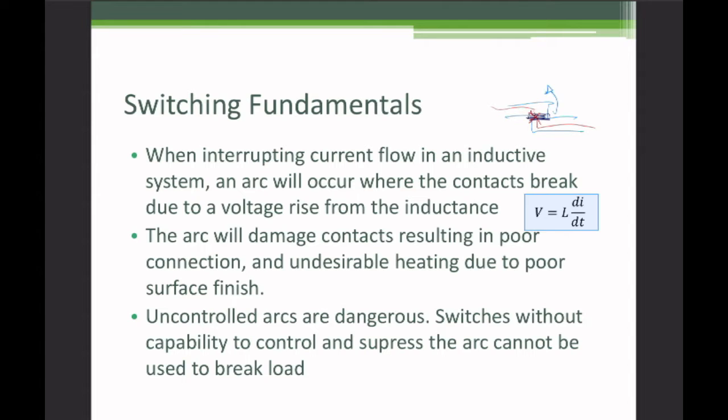In the best case, your contacts lose their temper and sort of burn away from each other. In the worst case, your switch contacts weld shut, and now your switch isn't a switch anymore. It's just a hunk of steel or copper or aluminum, and you go to open it and it will not open. All of these conditions are potentially dangerous and to be avoided.